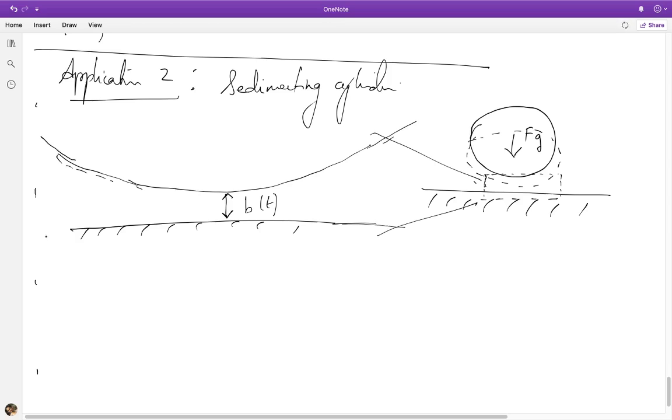The extension is not very clear, but it extends over some region where you can use the thin gap approximation. If you go further and further away from the narrowest point, you will ultimately go into the outer zone where the thin gap approximation fails. So where exactly the domain for the thin region is not very clear, but as you will see, those details don't really matter, and it's even something that you can keep adjusting as the cylinder approaches closer to the wall.